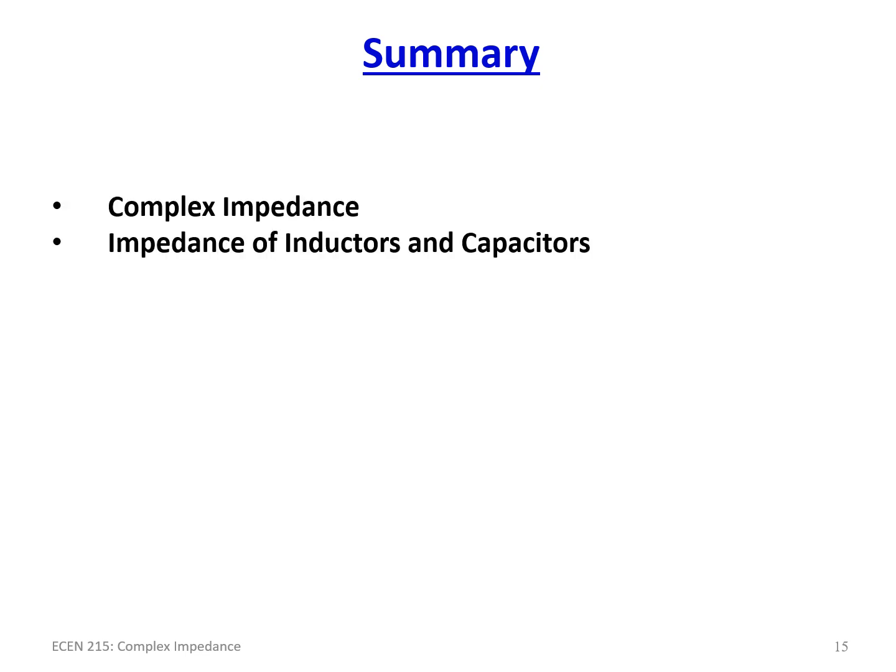So in summary, we learned about complex impedances, and specifically, we learned about the impedance of inductors and capacitors. So now we've taken the concept of phasors, and now we're applying it to the actual circuit components like inductors and capacitors, and also resistors. And as we learned with inductors, it was J omega L is the impedance. In the phasor math so far, we haven't seen omega have an application. This is where omega comes in.